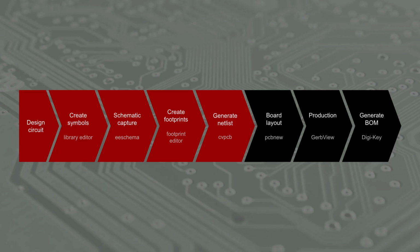Over the last few episodes, we created a custom schematic symbol, created the schematic, made a custom footprint, associated footprints with schematic parts, and generated a netlist. We're finally moving into the layout stage with pcbnew. Here, we'll import our netlist, arrange our parts, draw a board outline, and make trace connections.